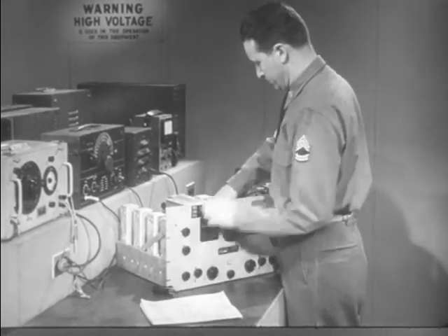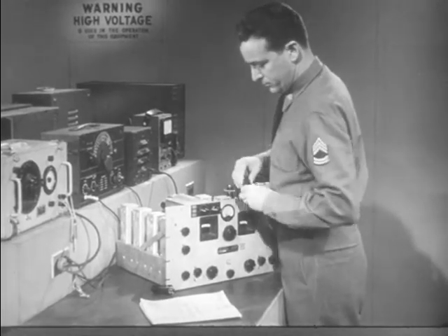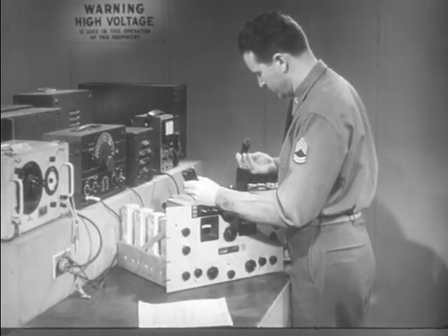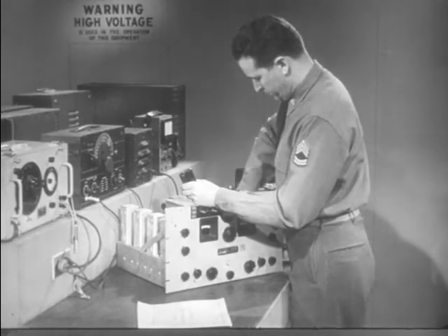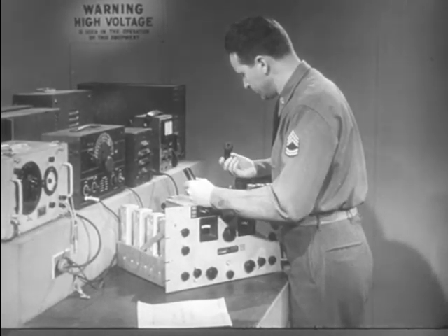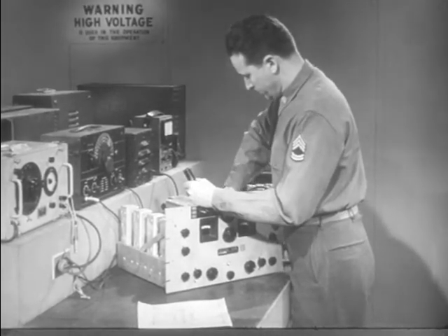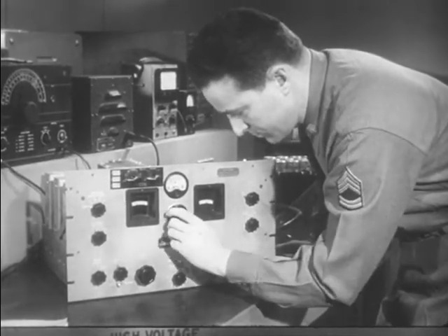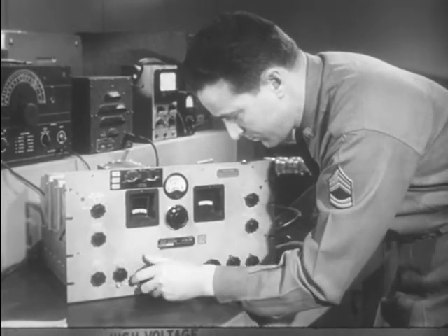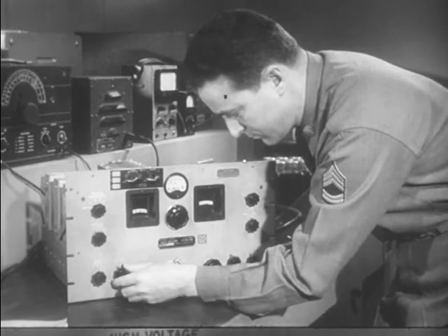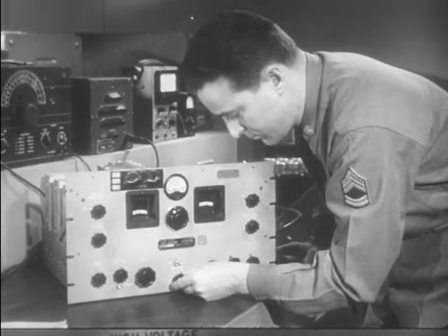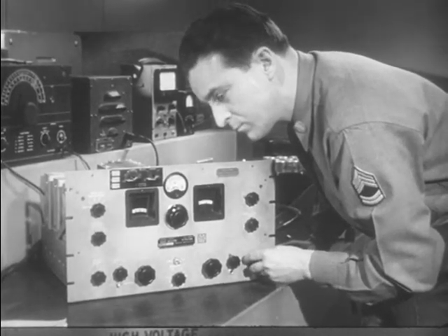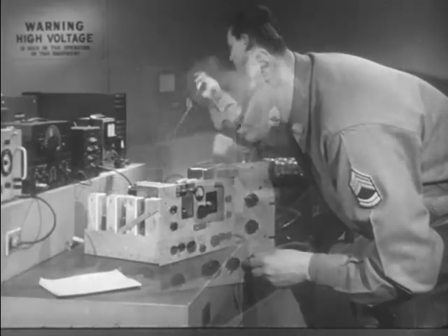Now returning to the radio receiver, before it can be aligned, it must be checked thoroughly to eliminate all other defects. Tubes are checked, voltage tests made, and a careful visual inspection accomplished. Aligning a set that has other defects only means repeating the whole process again, since change in the constants of the set, such as a new tube or capacitor, affects the alignment. So repair first, align last. If a receiver is not normal after all other defects have been eliminated, it probably needs alignment. This is particularly true if the receiver shows any of these symptoms: weak signal strength, lack of selectivity, or incorrect tracking. That is, the frequency marking on the tuning dial is a great deal different from the frequency of the transmitted signal.